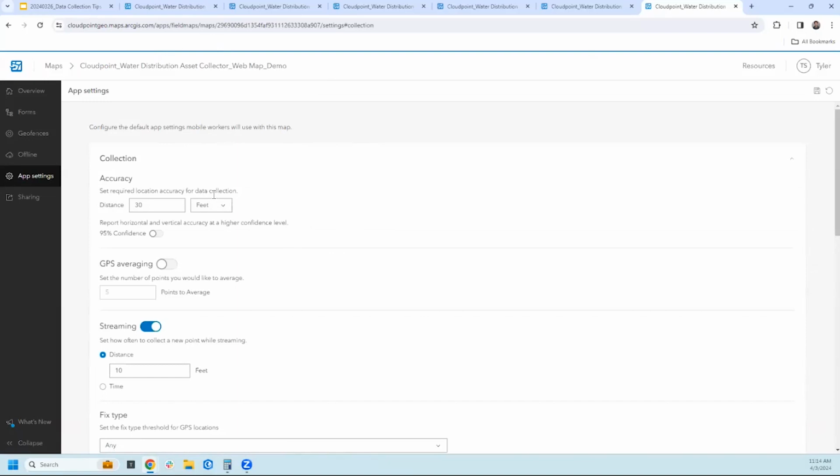For accuracy, this is just a threshold. When I'm out in the field, I usually set this somewhere around 6 inches. What this does is, while you're averaging with the DA2 and your accuracy is sitting at about 1 inch or so, if you're under some tree cover or for some reason weather-wise your signal jumps up, it will automatically pause what you're averaging.